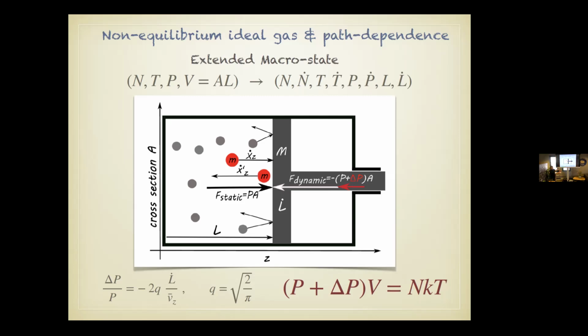If you take a piston, a cylinder with gas in it, and you want to compress the gas, then to do that in finite time, you need extra pressure. If you have infinite time, you just hold the pressure, and with no additional pressure on the piston, I'm not moving the piston at all. In order to move it, I need to add a little bit of extra pressure to push it in. Now I've invested work into the system.